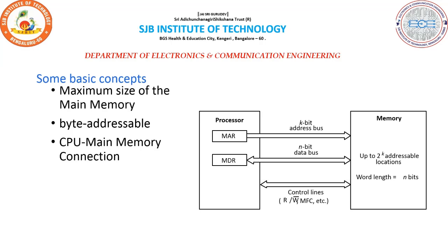In a read operation, the other bytes may be fetched from the memory, but they are ignored by the processor. If the byte operation is a write, however, the control circuitry of the memory must ensure that the contents of the other bytes of the same word are not changed. Data unrelated to the execution of the program can be discarded by the processor. It has to retrieve the proper data which has been stored in the particular address specified by the processor.